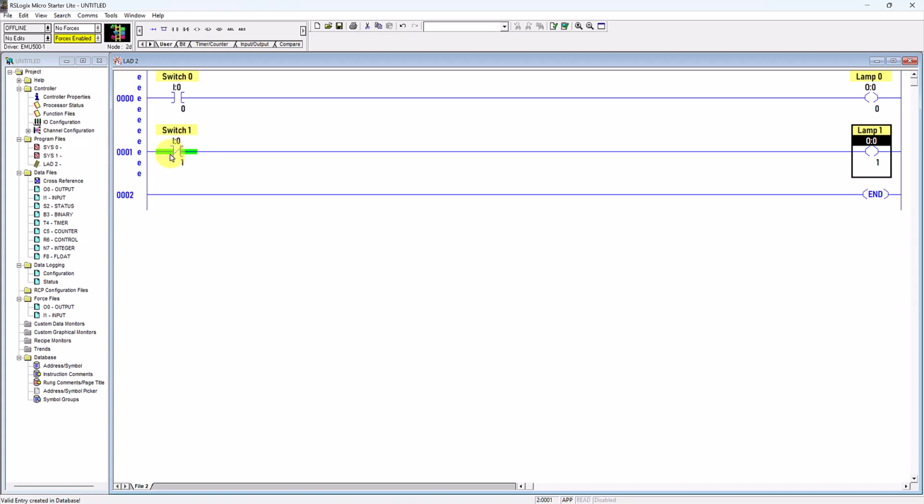Hence, this normally closed virtual switch will remain closed, and the virtual power can flow through and energize this virtual output coil 1, and thus will cause the digital output 1 internal normally open switch to trigger to close. Hence, the current can flow through this digital output 1 circuit, and it will activate the external load such as the contactor, relay, buzzer, etc.